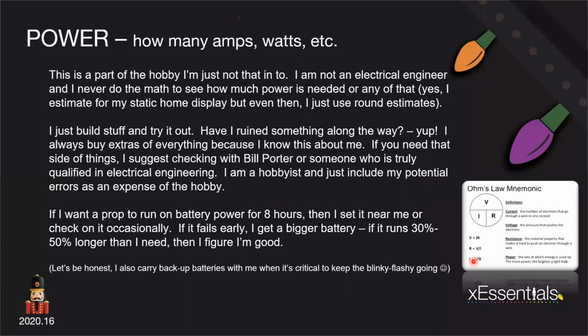So usually the next question that comes up is how many amps, watts, etc. I wrote this out and I'm just going to read it. This is part of the hobby, to be honest, I'm just not that into. I'm not an electrical engineer. I never do the math to see how much power is needed or any of that. Yes, I estimate for my static home display, but even then, I just use round estimates. I know that my 5-volt power supply, when I'm running at somewhere around 30 to 40% brightness, I can run about 1,500 pixels off it. And that's giving me plenty of headroom.